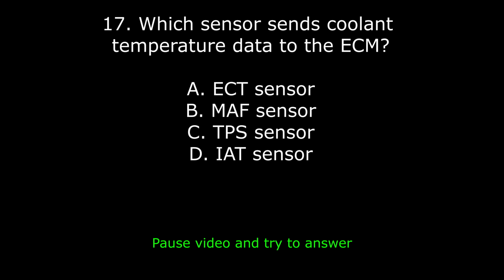31. Technician A says DTCs can be cleared by disconnecting the battery. Technician B says some modules retain codes in memory. Who is correct? A. A only. B. B only. C. Both. D. Neither. Answer: C. Both. Some systems reset with power loss, but others store non-volatile codes requiring a scan tool.